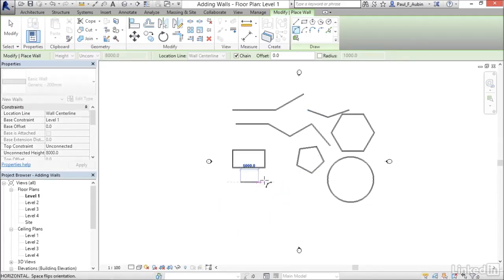In AutoCAD, you would draw along the curve, but in Revit, you actually draw the start point and then the end point, and then notice that you're actually creating the radius of this arc. So if you're used to using another CAD program, then you really want to pay attention to the prompts that appear when you're doing this the first time and practice it a little bit.